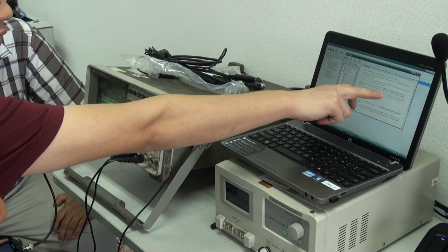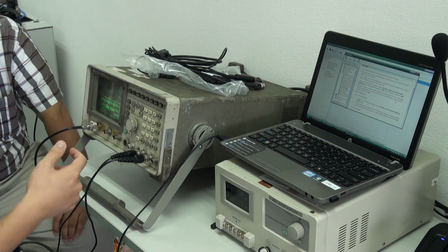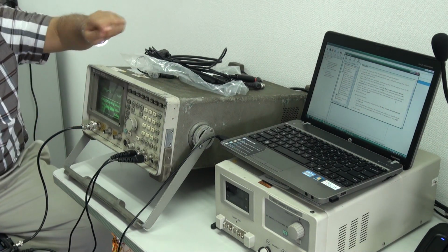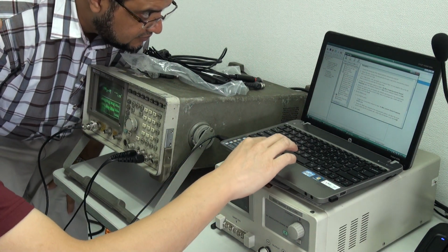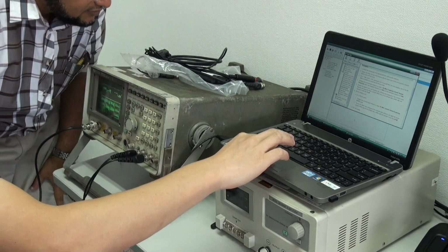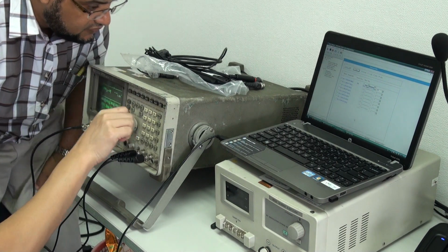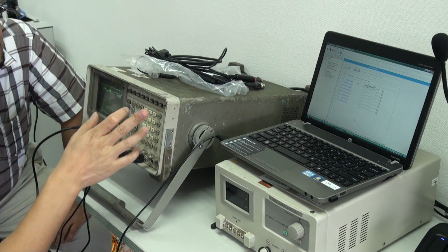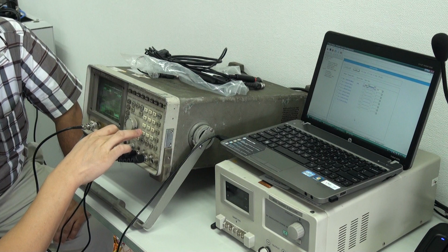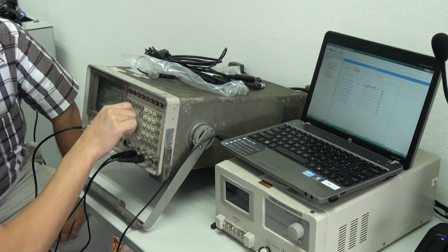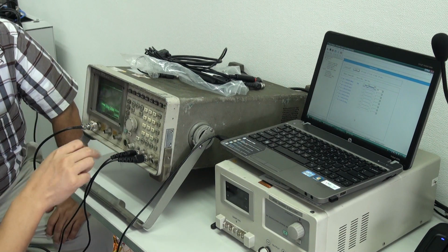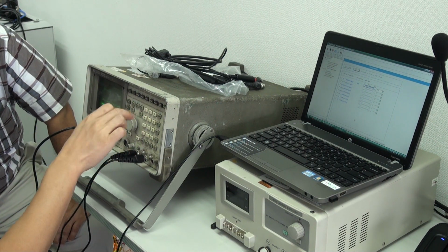to 1 kHz and the modulation deviation to 3 kHz. And squelch, is there any squelch? Adjusting to open it, yes, of course. And then you need to set the frequency. The first one is 330.075. And the amplitude here is minus 118.